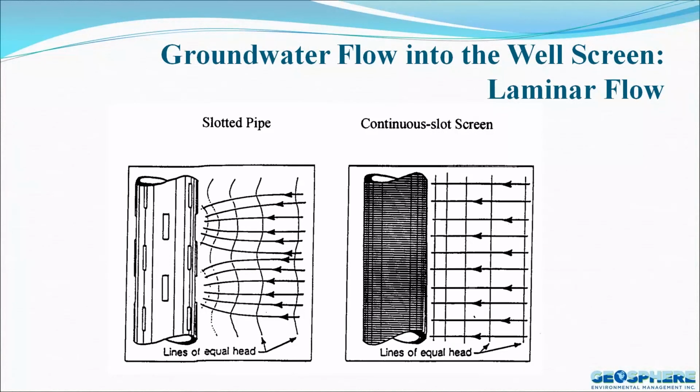They're fighting with each other, creating more turbulence as the little particles go in there. Whereas the ones on the right, a little bit more harmonious. They try to flow in there. They're radially flowing into that well screen. They're working with each other a bit more nicely and creating a better environment, minimizing a lot of the problems which can occur around that well screen.